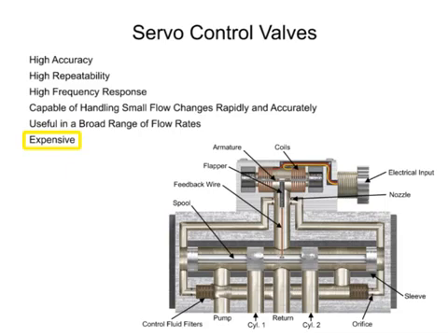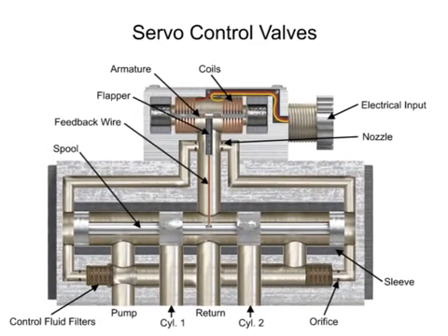The main difference between proportional and servo valve circuit design is that servo systems have a method of feedback that assures that the actuator is doing what the controller tells it to do. Most industrial applications use feedback from electronic linear, rotary, or force transducers. A transducer is a device that produces an electrical signal in direct relation to a position, force, or speed.